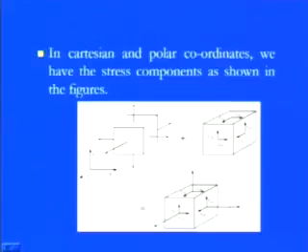And if I add these to the shear stress component, if we are working in this domain, which is my z domain, then in that z domain, what are the shear stress components? Tau zy, because y is the top side, and z is the area where the cutting plane is, the normal to the cutting plane. So this is my tau zy in the vertical, and in the horizontal way it is tau zx.